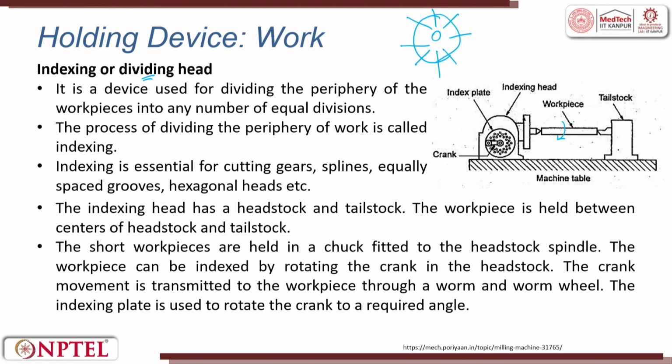Suppose there is a cutter which is supposed to make a straight groove. Now, I index. So, a cylindrical part can be made into a square by having this indexing mechanism. A gear can be cut by using this indexing mechanism. In the indexing head there is also an indexing plate. In the indexing plate there are multiple holes, and you have a crank to rotate it and locate it. Then the indexing plate will transfer the data to the indexing head. From the head it will transfer the data to the workpiece, and the workpiece rotates.